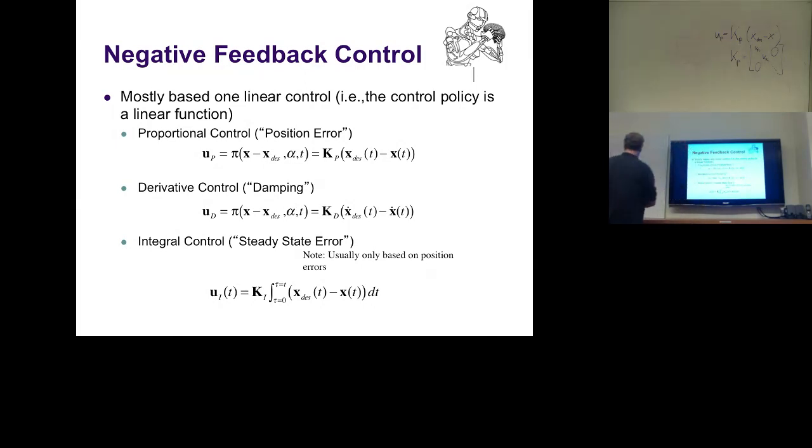So what is this thing doing? Let's look at this idea for one moment. If you are a very simple system here, living on this axis x, and let's make this here your x desired. Now let's assume you're currently here at this point. It means x desired minus x, this point here, is going to be greater than 0. If it's greater than 0 and you multiply this with a positive constant, then you create a force which pushes you towards the goal. Perfect.